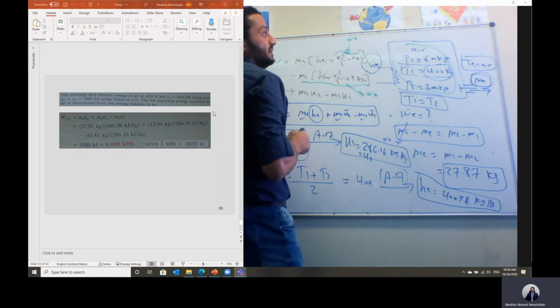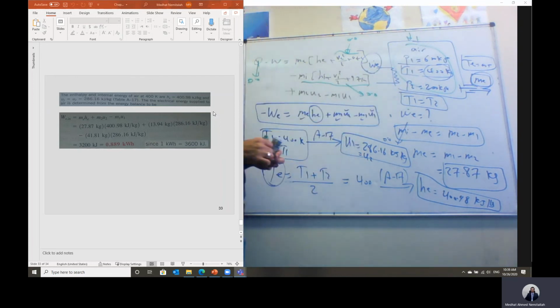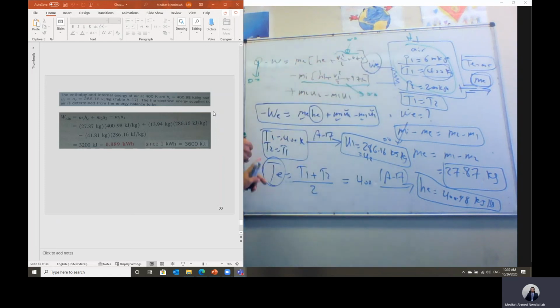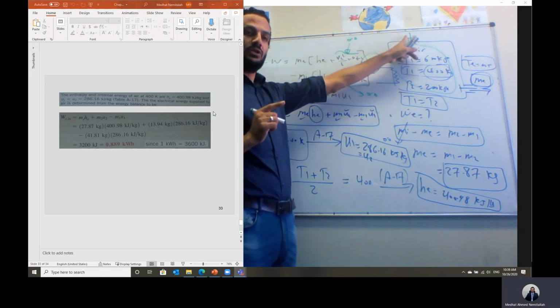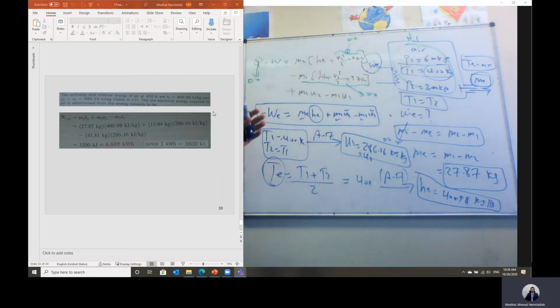We can also do the same if we have flow at the inlet and we don't have an outlet. You can calculate the inlet temperature as the average of the initial and the final temperature in case the working fluid is air. But if it is steam or refrigerant, the condition at the inlet section or the outlet section will be given for you, with two independent and intensive properties. But in this case, we have calculated everything.